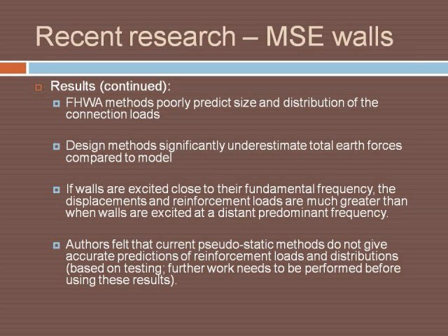They also found that when walls are excited closer to the fundamental frequency, the displacements and reinforcement loads are much greater than when excited about a distant predominant frequency. And the authors felt that the current methods do not give accurate predictions of reinforcement loads and distributions based on current testing. They felt that further work needed to be done before they could use these results.